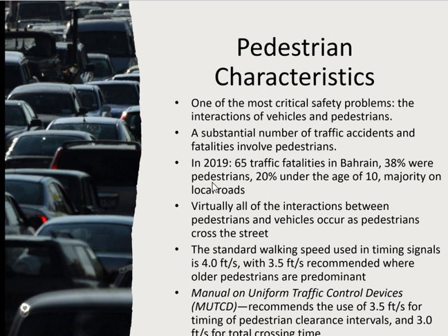The recommended speed starts from 4 feet per second, which is considered on the higher side. If the pedestrians are fit and normal, you can take up to 4 feet per second. But if most of the pedestrians are old and need help to move, then the lowest value is 3 feet per second. These values are given by MUTCD, the Manual on Uniform Traffic Control Devices.